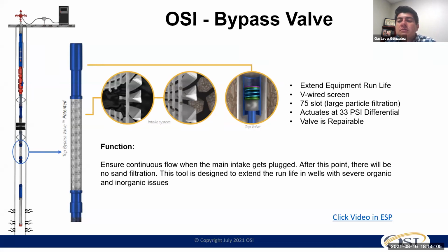What I would suggest, based on the history that you're facing, is that you have to tell your ESP provider, this is the problem that I'm facing. They're going to give you multiple scenarios. So based on the volume of sand that they see in the flowback, we go back and tell them, this is the ratio that we're producing in this field or these particular wells. And you're given an estimate of the sand that the ESP is going to start lifting and facing.